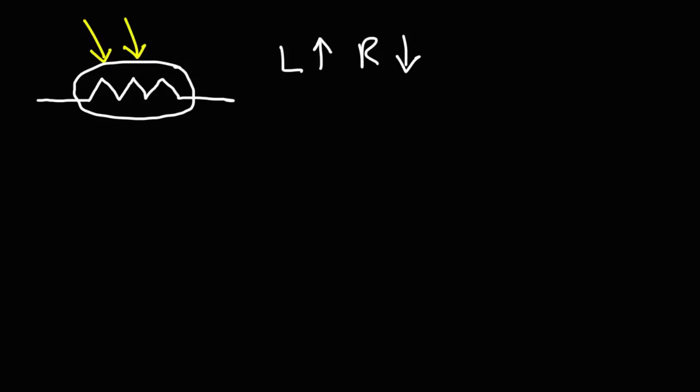And this is very useful because let's say you have one of these night lights in your home, when you turn off the light, these lights will activate. So your house is not very dark where you can't see where you're going. It's very useful to have these in your home, especially if you're coming home at night and you can't see where the light switch is. Having these night lights active at nighttime where it's not so bright but bright enough so you can see where you're going, they're very useful. And so this circuit element, the light dependent resistor, is very useful for creating night activated LED circuits.